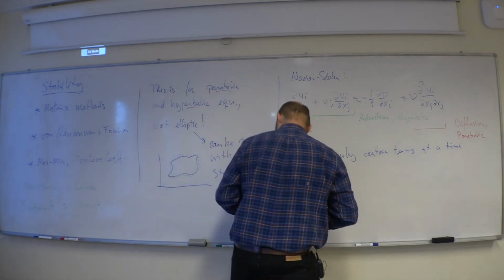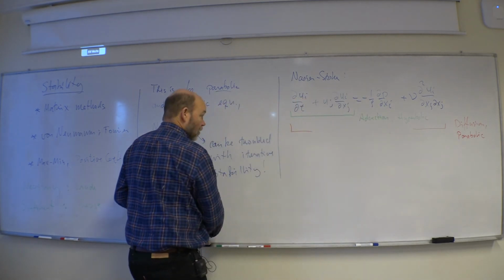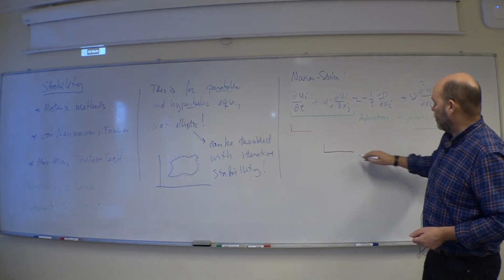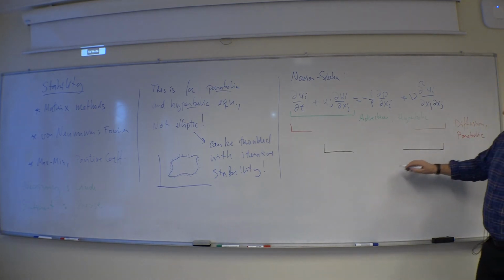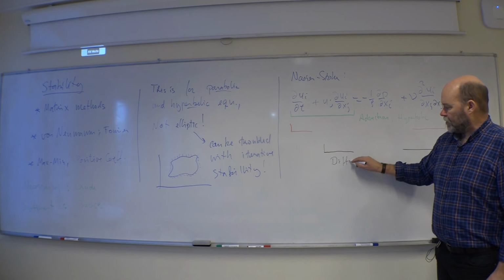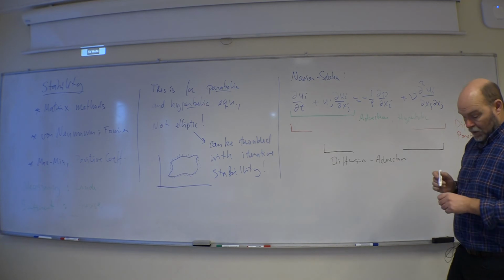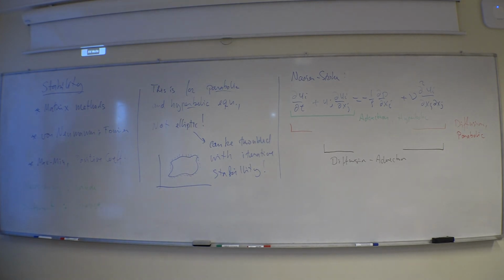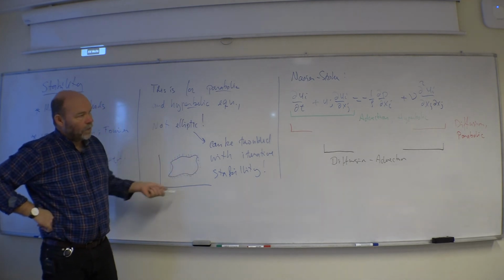Taking the advection term and the diffusion term. So then we are using, say, a diffusion advection equation. But it's a steady state equation, so not parabolic, not hyperbolic. So it will actually be of an elliptic nature. You have to specify it with boundary conditions all around.